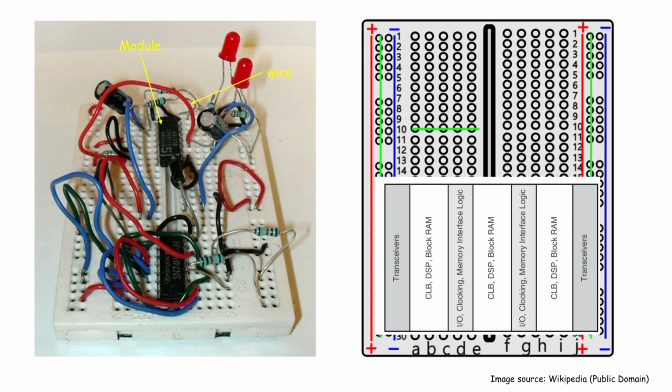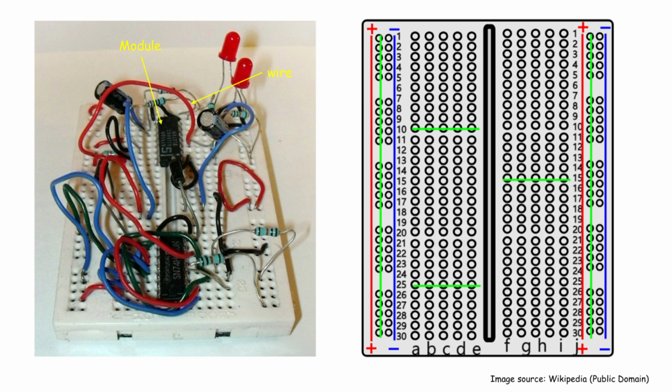In some devices, you'll also find an embedded ARM processor. These are known as SoC, System-on-Chip, FPGAs. So while the internal architecture may seem complex, at its core, an FPGA is made up of programmable logic and interconnects that you configure to create any digital system you need.